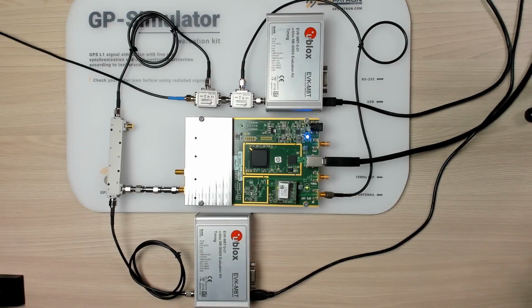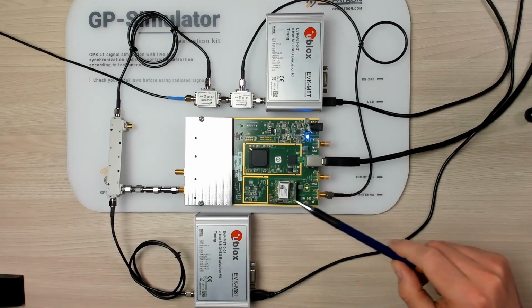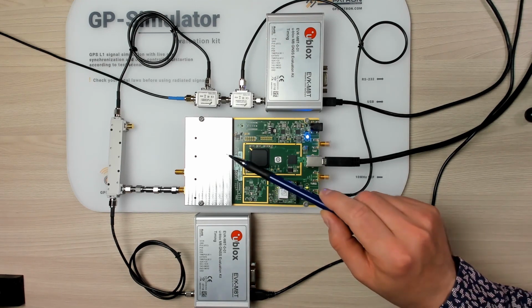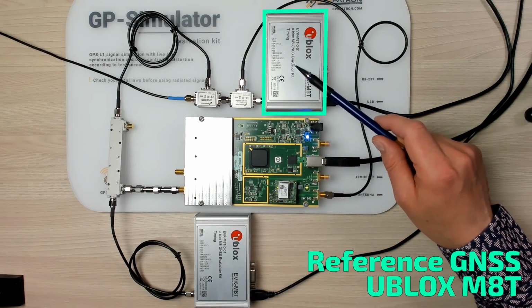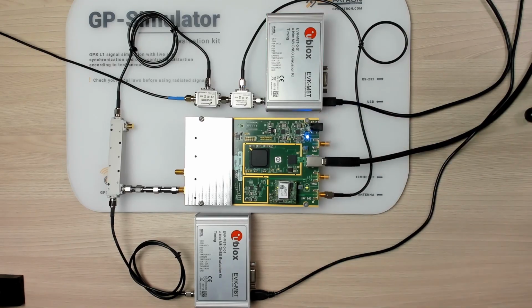Okay, what we have here. To use the application, you need a software-defined radio from Ettus Research with an embedded GPS disciplined oscillator. In my case, I use the USRP B200 board. Also, you need a GNSS receiver from u-blox. It's needed to get live GPS signal parameters, and it's used as a reference in our tests.